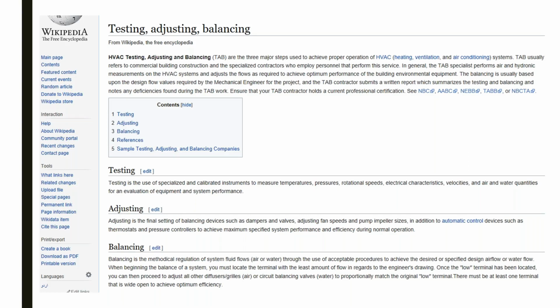No. Well, there could be, because if you don't get the right airflow, if you don't have the right air changes in the space, you'll never get to set point. So if you don't have enough air going in there, or you could have too much air going somewhere else and it's starving them over here. Like the people who are changing the controllers, they're running out of air because they didn't understand that they had to make adjustments when they replaced those components. So they did it to themselves to the point that now they have to do a full TAB and retro commission that building to get it back to where it needs to go.